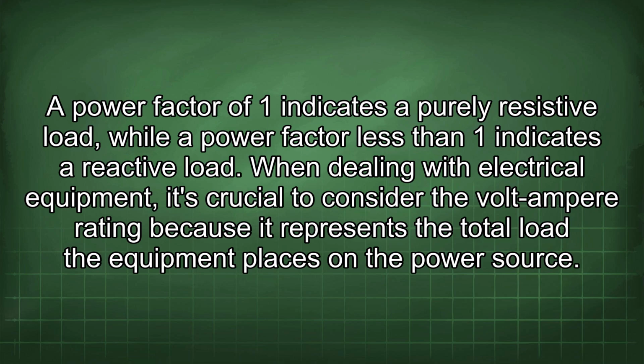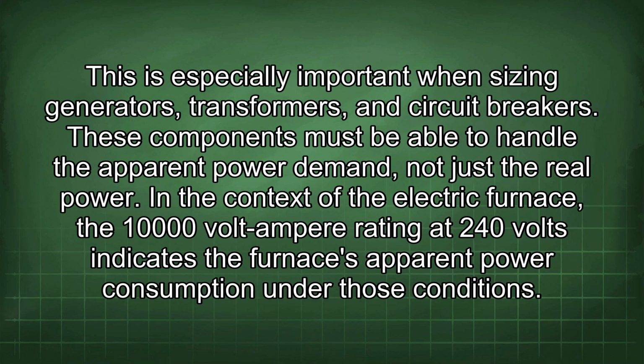When dealing with electrical equipment, it's crucial to consider the volt-ampere rating because it represents the total load the equipment places on the power source. This is especially important when sizing generators, transformers, and circuit breakers. These components must be able to handle the apparent power demand, not just the real power.